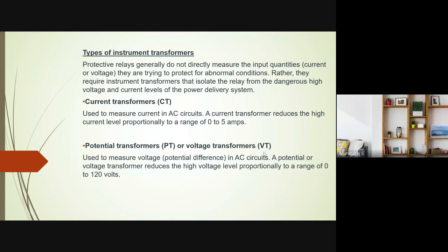I hope this point is clarified, because why I am explaining this phenomenon is that basically 95% of the loads in industries are only motors. So based on the motors, the protection schemes are arrived at in industry, and based on the starting current, the various types of protections are introduced for motors.